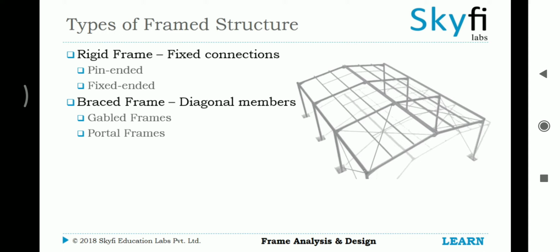Portal frames are generally low-rise structures, comprising columns and horizontal or pitched rafters, connected by moment-resisting connections. This form of continuous frame structure is stable in its plane, and provides a clear span that is unobstructed by bracing, which is useful for construction of industrial and commercial buildings.